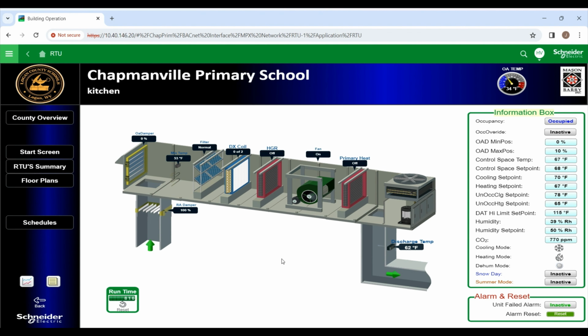It will start on a certain speed, and then once it picks up the heat or the cool mode, it will automatically ramp up to speed. But on your end, you will see it's on or off. You're not going to see what the speed is. But you can determine that just by looking at the system. If it's in heating mode or in cooling, that will tell you if the fan is actually at a higher speed or not, if that makes sense.